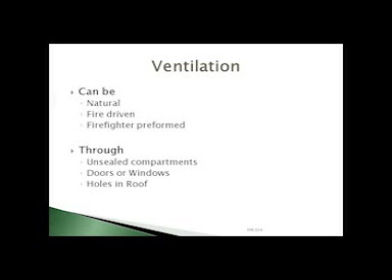And third, we have firefighter performed. As a firefighter myself, I've done a lot of ventilation. Generally, what this is done for is to move the heat and the smoke to make conditions more tenable inside. The goal is, one, to make it safer for the firefighters themselves, to control the fire, and if anyone's alive in there, to keep them alive. Generally, it's done through a roof, if possible, but that doesn't limit it to a roof. It can go through doors, windows. We've cut holes in walls. It's all about where the fire's at and how you can get the heat out.